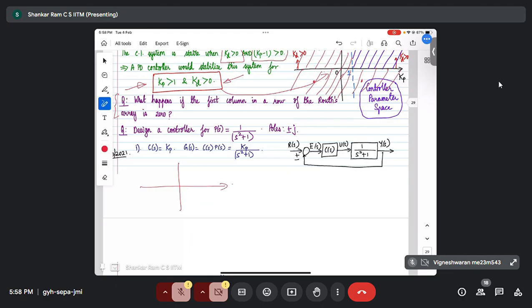Let's say we have the S plane, this is the imaginary axis, sorry about that. So now I'm looking at the complex plane. If you have a root at +2 and a root at -2, they are called radially opposite roots. Why? Because they are equidistant from the origin, 180 degrees apart, right? Similarly, if you have a root at +3j, -3j, that's another case of radially opposite roots. Then you can have these 4 roots that form a set of radially opposite roots, because you can draw a circle centered at the origin. So you can have all these cases of radially opposite roots.